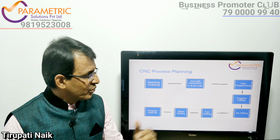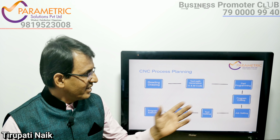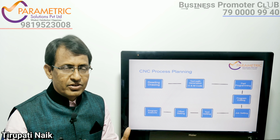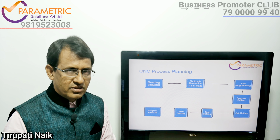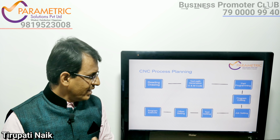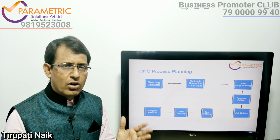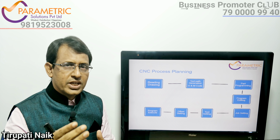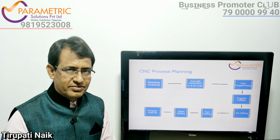And then we have to do the part programming, and the program editing according to the drawing we read. Then we do the job setting on the CNC machine, and then proper tooling on the turret, and then taking the offset for workpiece zero, and then executing the program, and we run this program accordingly.